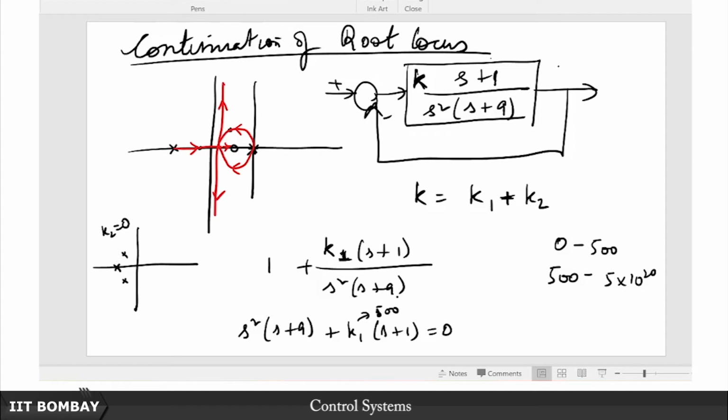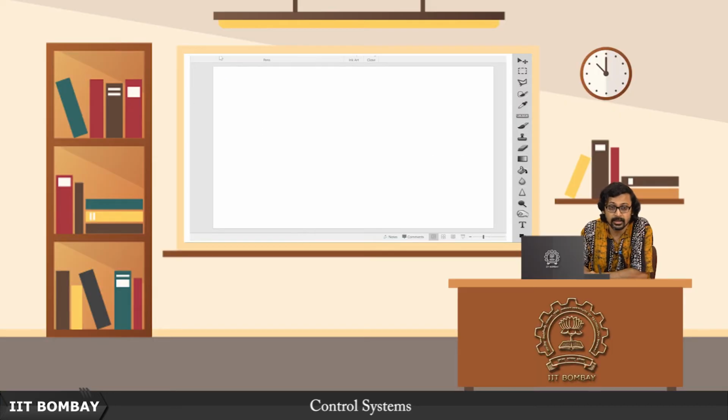So I split it up into two terms, I ramp up one term to its highest possible value while keeping the other term off, and then I see where the roots have migrated, alright, and then I call them my now nominal system. Only when K2 starts to be effective, from that point onwards, that is my nominal system, okay. So by the same token, where am I getting with this, now you might ask.